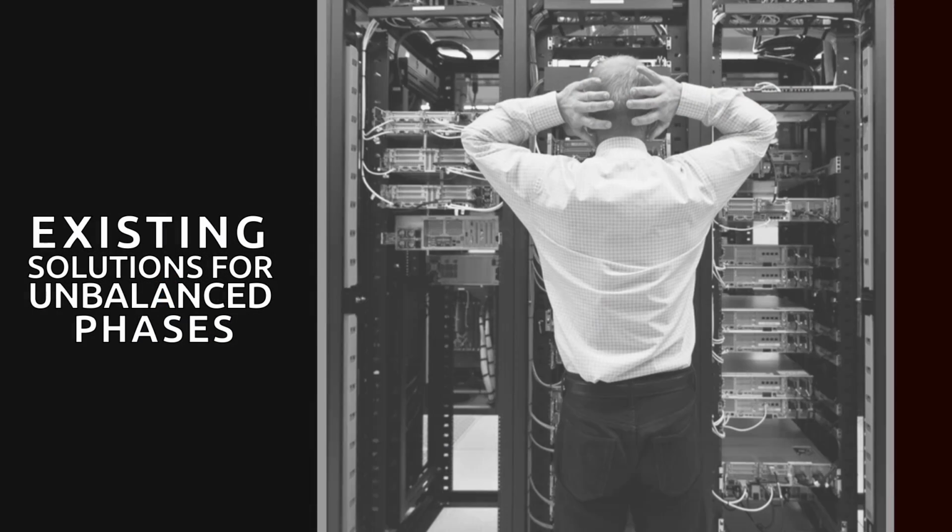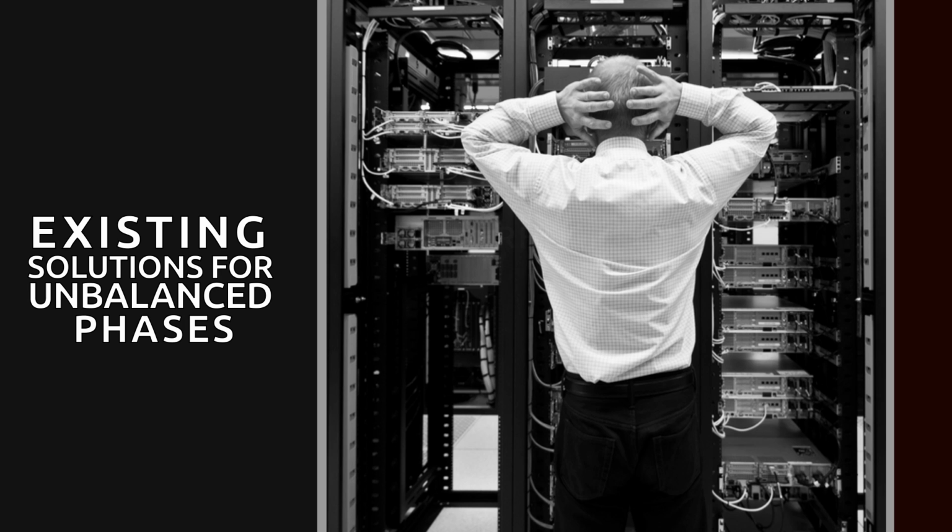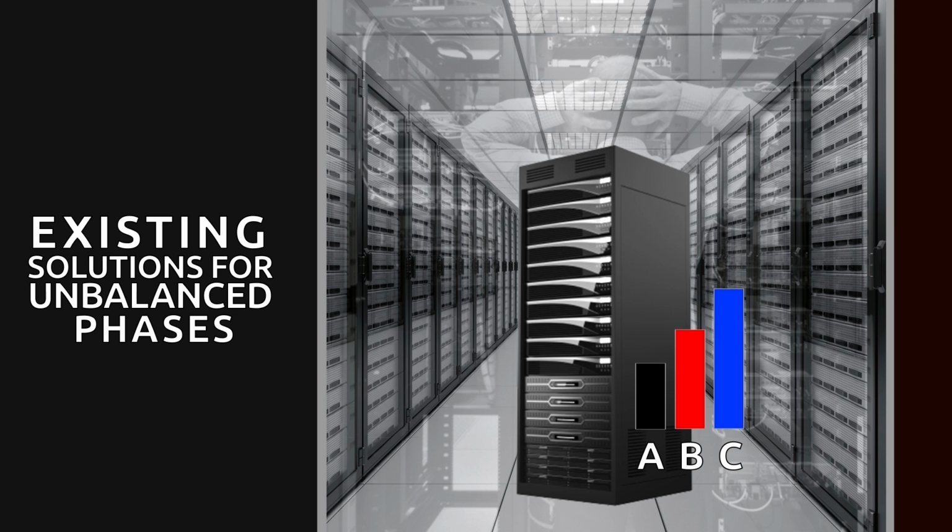The existing solution for unbalanced loads revolves entirely around manual manipulation of the electrical network and introduces human error at multiple levels. Most data centers attempt to manually balance the server rack loads across the phases by guessing the power consumption on each phase and hoping that it remains steady during operation.